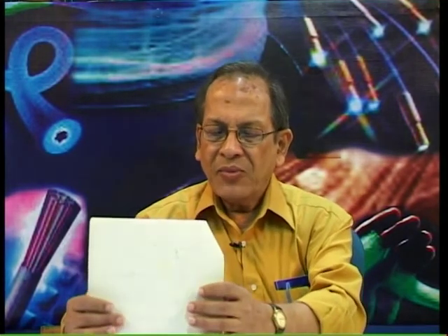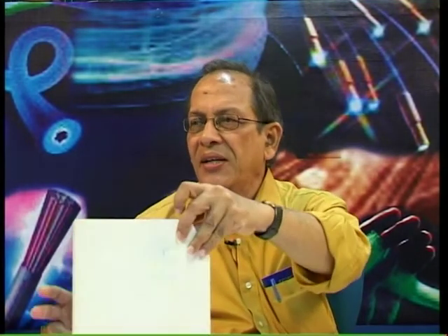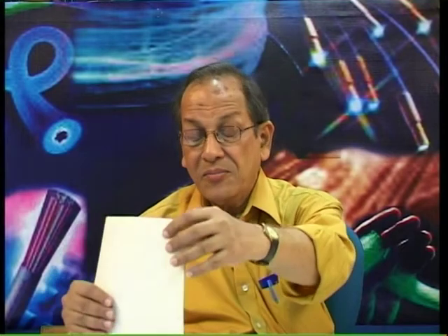How do you form an axisymmetric solid? Like a cylinder. How do you form a cylinder? You have a plane, rotate it about the axis, and you will get a cylinder. It can also be a hollow cylinder. And if the loading is axisymmetric, then every radial plane of this cylinder behaves in the same manner. So, why do we analyze the whole structure? We can analyze only the plane. So, the three dimensional problem need not be solved.